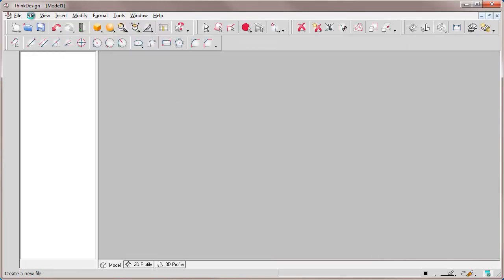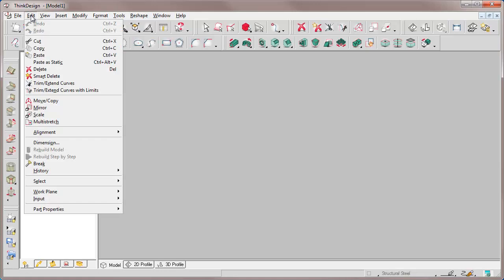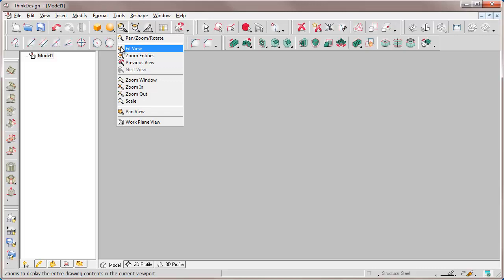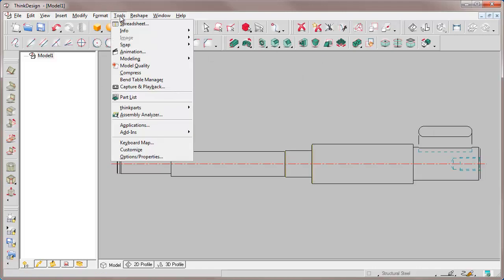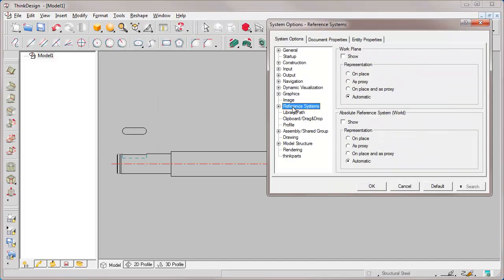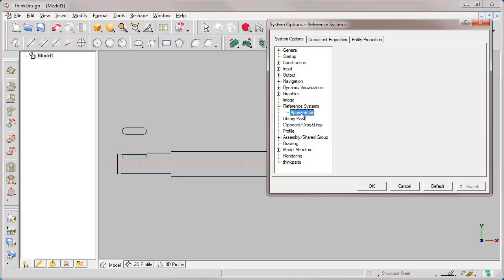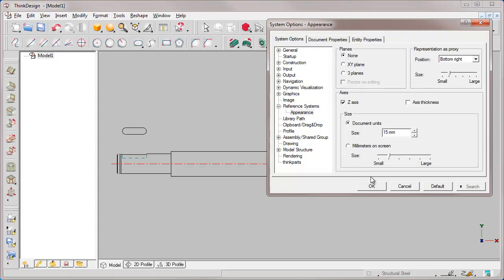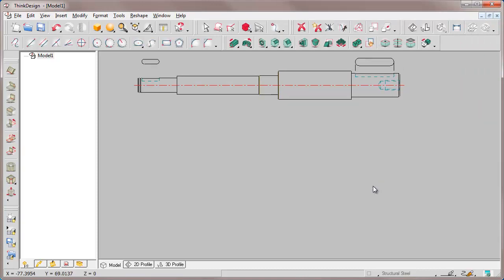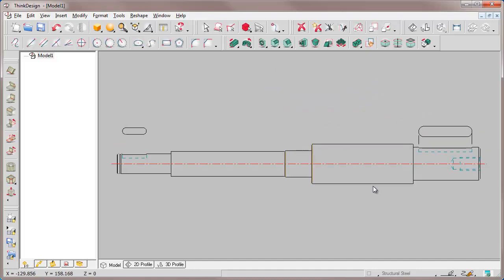Now we open a new model and we paste them. With copy and paste, the program places the geometries with respect to the origin of the drawing. If we display the set of the three axes, the distance of the entities from the workplane origin is the same that they have in the drawing. We turn off the visualization of the workplane and pressing the W button, we turn off the workplane too.